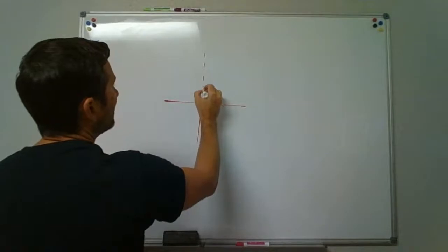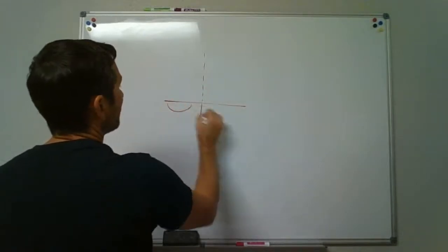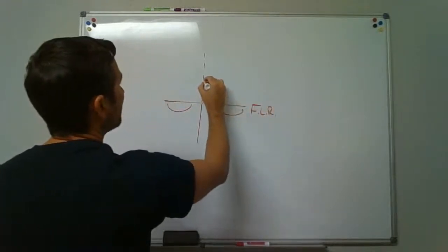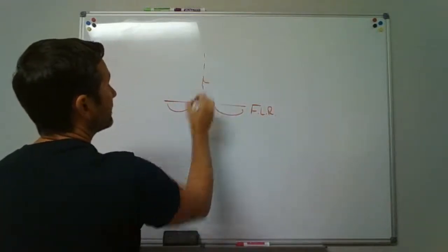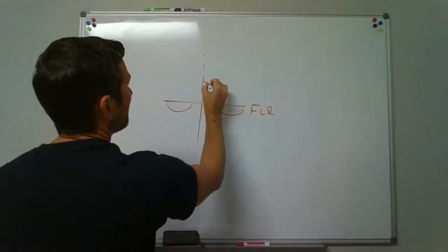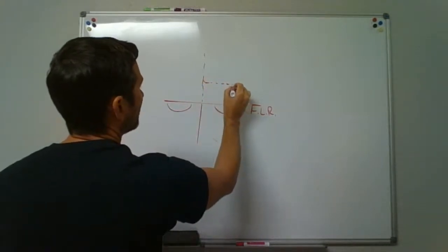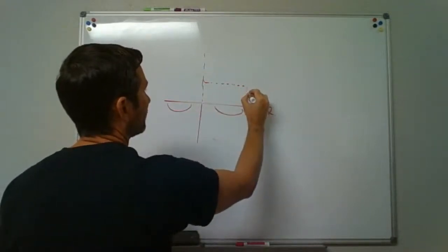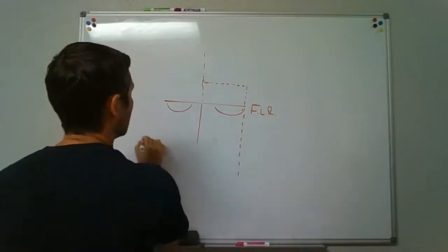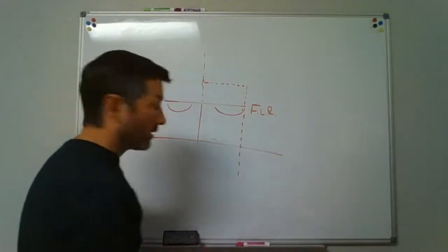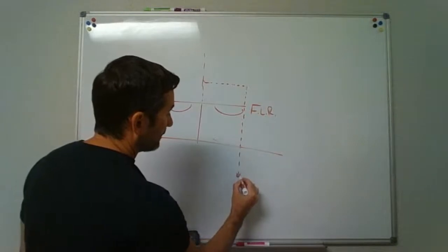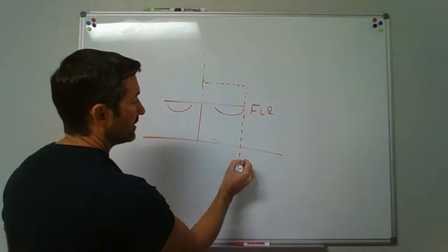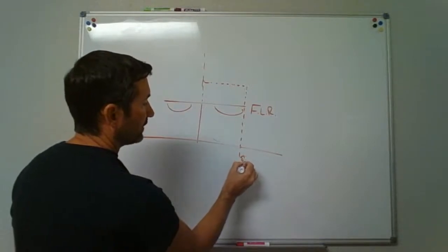So what I did is, if this is the flood level rim, I came off of that, and I'm at least 6 inches higher than the flood level rim. I put a T. I came over a little ways, stayed out of the way of electricians and anybody else's stuff. But I took that vent, and I went down below the floor, and I put a permanent PVC cap on that, glued it on there, and on the side I wrote "future vent."